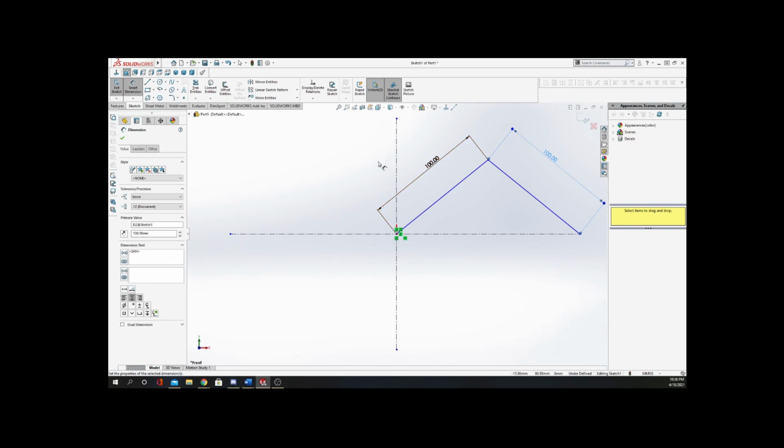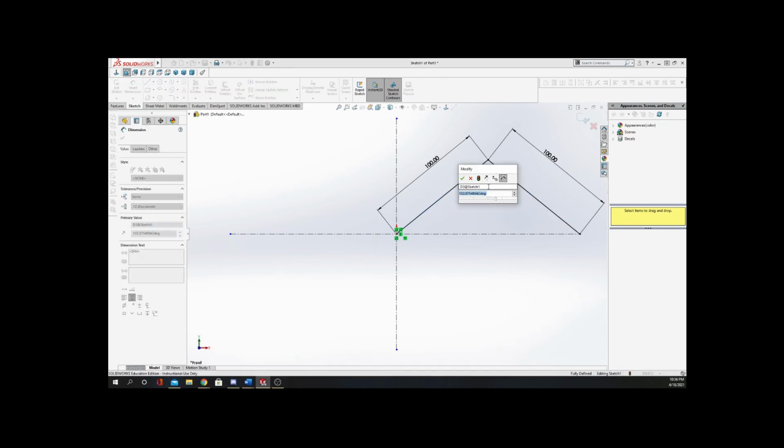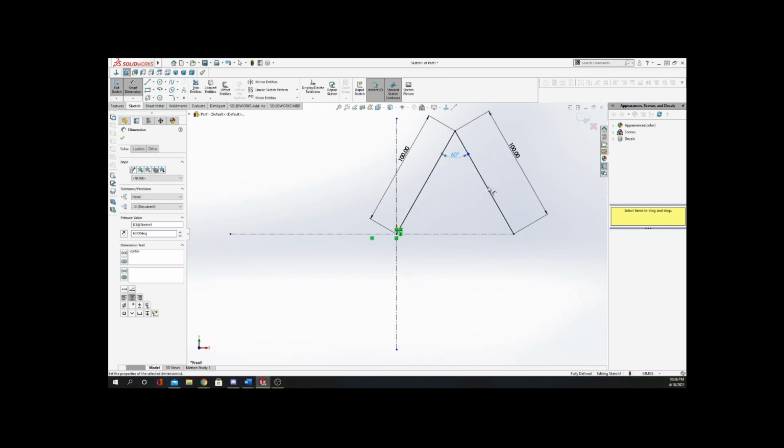And then what we can do inside of Smart Dimensions is choose length, but we can choose angle too. So if we go to Smart Dimensions and click on this line and then click on this line, it drops us down and we get our angle here. Say we wanted to do an isosceles triangle. Well, we already have two sides that are equal to each other, right? So if we put a 60-degree angle in here, that brings this up, and now this length from here to here should also be 100.